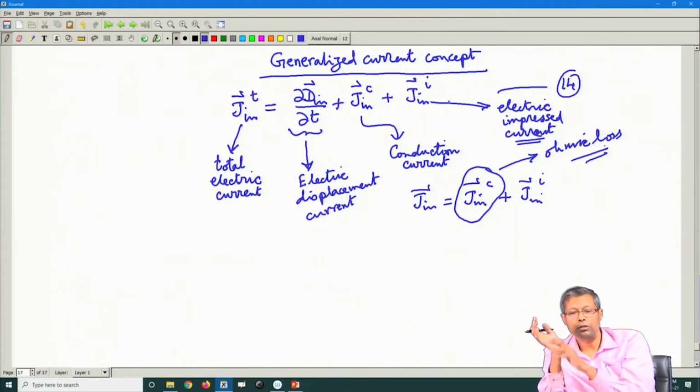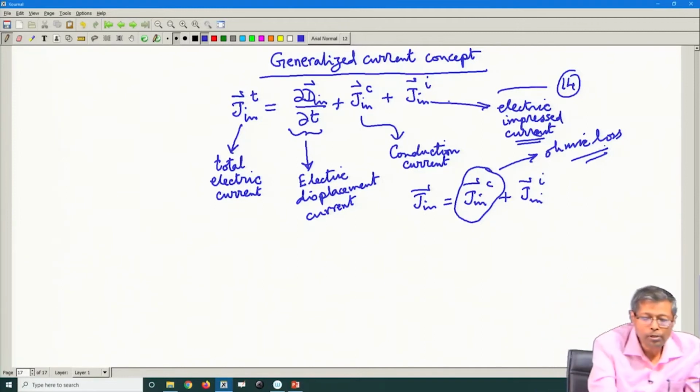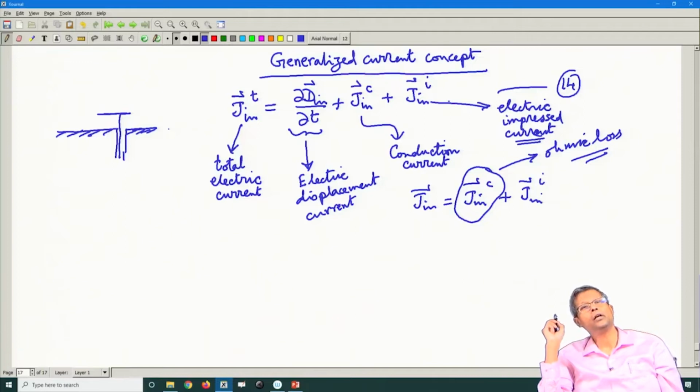We will come to that, but this is a very important concept. Why is it an important concept? Because you might feed power to an antenna, and you might see that the antenna is giving a very acceptable reflection coefficient, no reflected power. It does not mean that the antenna is radiating. For example, if I have a structure like this, again I feed power. Particularly, this can happen in a miniaturized antenna scenario, where the efficiency of such an antenna degrades.